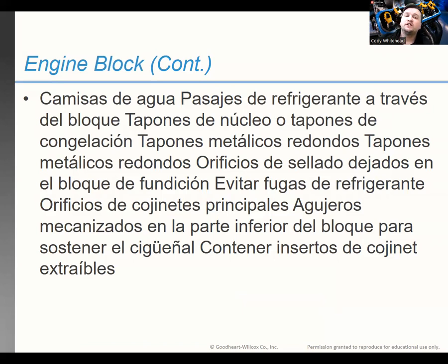Right? We have core plugs or freeze plugs in the cylinder block. If for whatever reason that coolant freezes, water, when you freeze it, it expands, right? We learned that in science. Well, to keep that expansion from damaging the engine and cracking the cylinders or the block, we have these plugs in the engine that will be pushed out if that happens. If something wrong happened and our coolant froze, that way it can relieve that pressure and save the block. And we can replace those freeze plugs. They're a little bit better than replacing an entire engine.